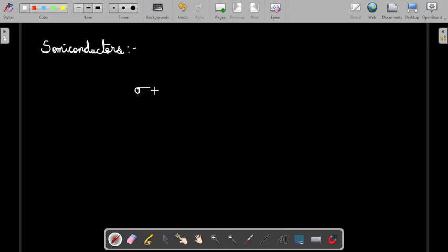Conductivity is a parameter that is generally present for every material. In a semiconductor, the conductivity is caused by both P charges and N charges, like N type material and also P type material. Electrons and holes both contribute to the current or conductivity in semiconductors. So in general, we use both n and p in the semiconductors: σ = nqμn + pqμp. We have already seen those things.